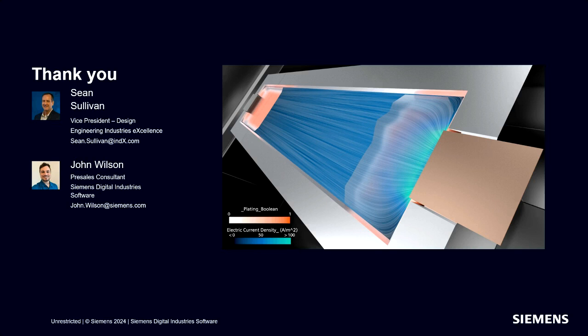So you have to do things like this. You can make changes to the battery cell, but you need to make sure that you are able to maintain the desired energy density or other requirements. And these are all parameters that can be changed within Battery Design Studio. These geometric changes like the thickness or the number of layers. You can even make chemical changes if you want to the materials.